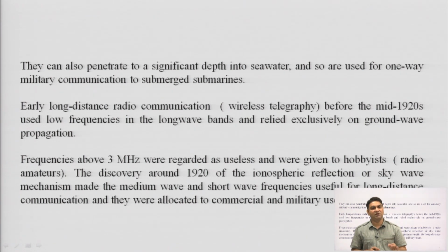The answer is that the ground losses at higher frequencies are so much higher that signals of higher frequencies cannot survive in ground wave propagation. They cannot travel along the curvature of the earth, they cannot glide over the surface of the earth. That is why they cannot be a part of ground wave or surface wave propagation.